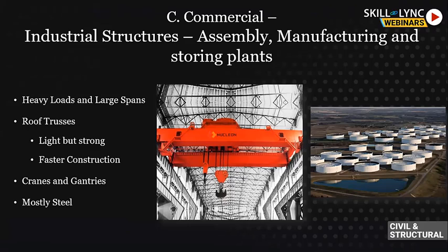Concrete, on the other hand, will require shuttering which will be standing for at least 10 or 12 days, basis the concrete strength that you're using on the top. And only then can you remove the shutters. The problem is the huge height, where the shuttering will be a difficult challenge.